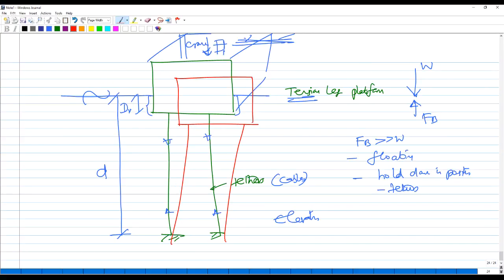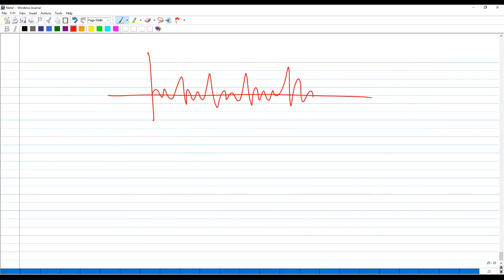You can see here, compared to the green picture, the red picture has a change in length in the tether. I call this delta T0. This delta T0 compared to T0 will have some change in length. This change in length will induce additional strain and additional stress. Depending upon the cross-section area, one can work out the axial load on this member. When this load history varies with time, it has different cycles of variation.